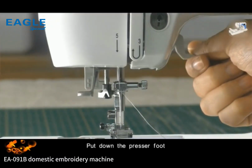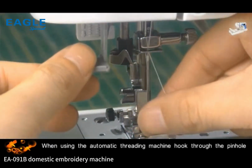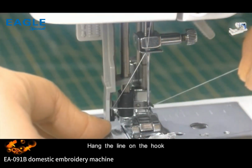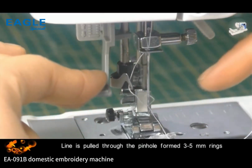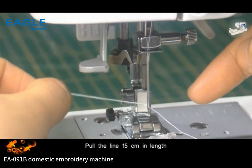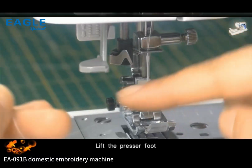Put down the presser foot. When using the automatic threading machine, hook through the pinhole. Hang the thread on the hook. Then loosen the thread rod. The thread is pulled through the pinhole, forming a 3 to 5 mm ring. Pull the thread 15 cm in length. Lift the presser foot.